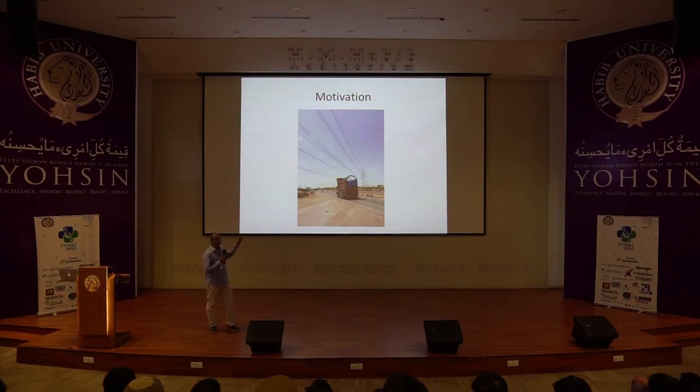No one has actually thought about what the distance is between this line and this truck, and how that changes over time. We can actually compute that. If we know how much power is flowing through this line, and we know the properties of this line, we know that when more and more power flows through a line, the line sags. The more power flows, the more it will sag, and also temperature-wise, there's more heat. In the summer, this line will sag more and more, and eventually it will touch that truck. So we want to find out how bad it can be, and when it will actually do that.